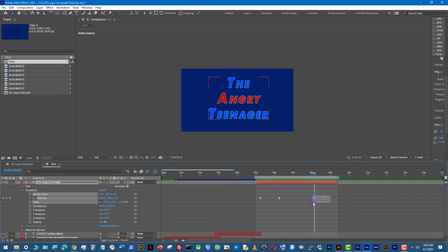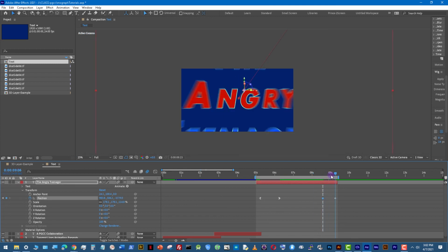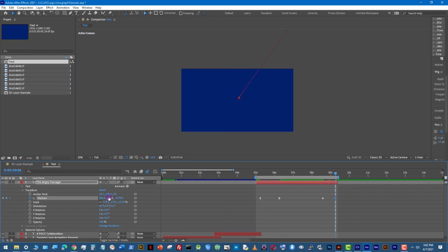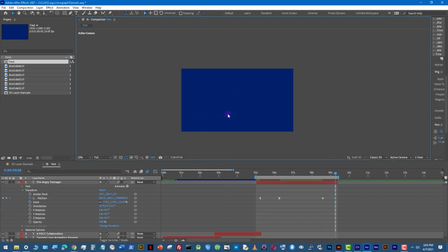I want it to maybe hang out a little bit longer and start going away, like in Star Wars. So I'll go something like 600. Actually, I'm going to punch in for the Z value on my position something like 6,000. 6,000, you can still see it. So I'm going to go incredibly ridiculous, 12,000. And now it's way out there in space, way away from the camera.